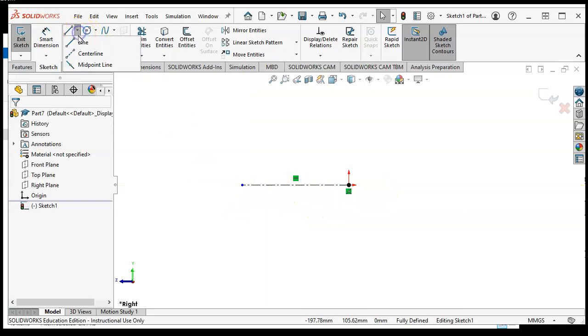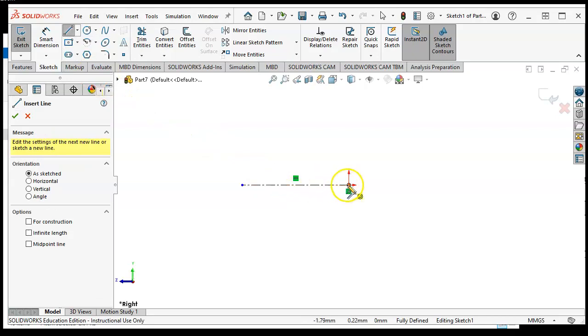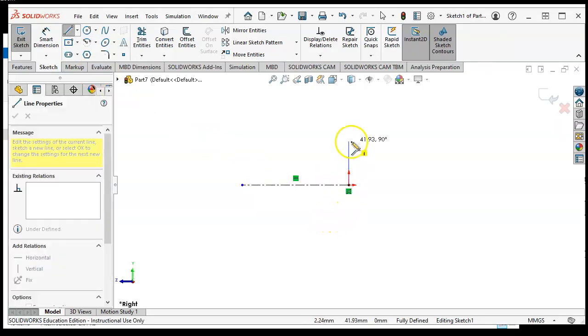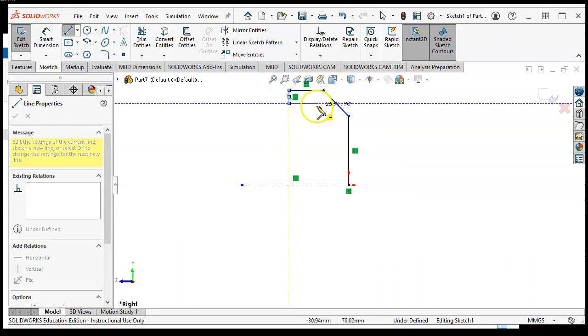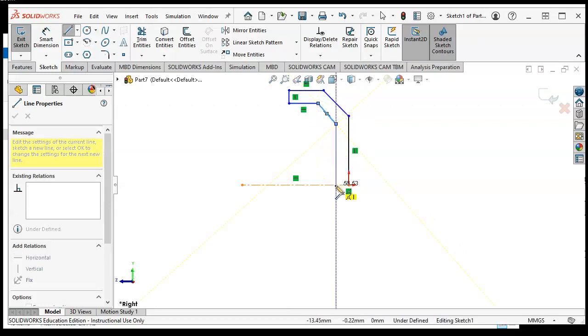And then we switch back to the solid line to create our sketch. When you're creating the sketch, don't be concerned about exact size at the beginning. Just create the shape that you want, the best you can. This is again a rough sketch, and we will come back and add dimensions, make it fully constrained. I'm doing only half of them.